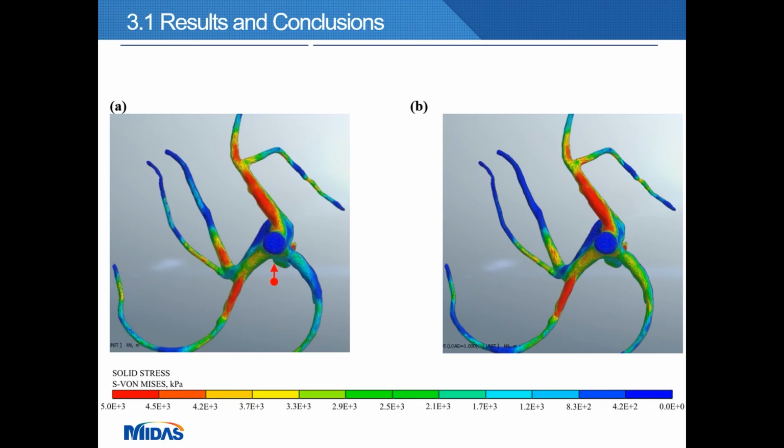First of all, you are seeing the stresses under a von Mises condition of the tree under the lateral load. This arrow is the direction of the applied load for the Samanea saman tree. The model for the Samanea saman predicted a dominant contribution of the main roots to the anchorage strength, whereas the secondary roots only develop around 10% of the maximum stresses presented in the main roots.